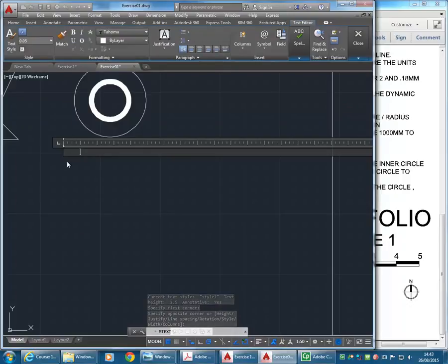And then I'm going to just type, with caps on, start a new drawing with the, not AutoCAD, AutoCAD ISO template. And let's make it look the way it does in the program. AutoCAD ISO dot DWT, just means drawing template.